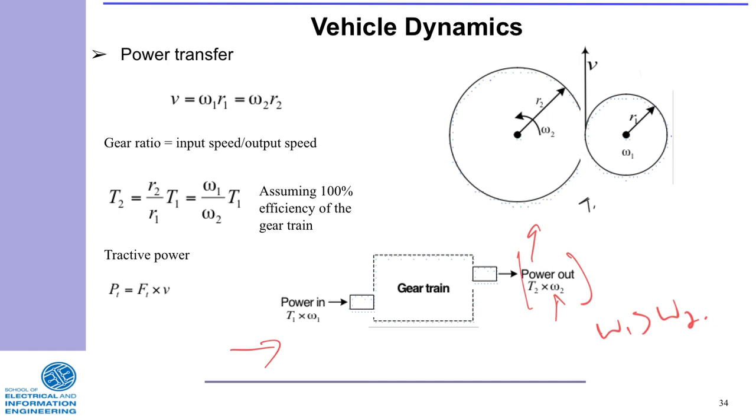All right, now the gears are defined, we can really define the gear ratio based on that equation because again, law of conservation, omega 1 R1 equals omega 2 R2. All right, and right there we get your relationships with the torques, assuming that it's 100% efficiency. So basically you're saying T1 omega 1 equals T2 omega 2, and then you play with the equations there. Right, so have this in mind.